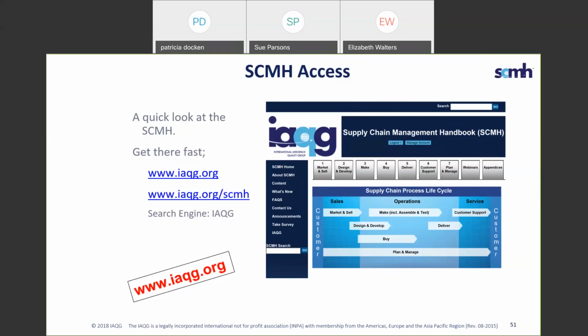Okay. Customer complaints are also inputs for the control plan. Please confirm. I'm sorry, what was that? Are customer complaints input for the control plan? Yeah, absolutely. In fact, that's a really good question, because if you get a customer complaint, you're going to go back and look at your PFMEA. You're going to see if it's been established in the PFMEA, and if it has been, what was the risk? What showed up for risk on that? Was that risk evaluated? Does that risk need to be reevaluated? Does that risk need to be added to your PFMEA? And that's what's going to flow into your control plan.